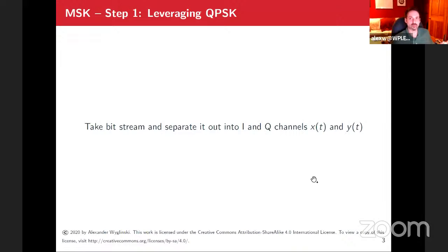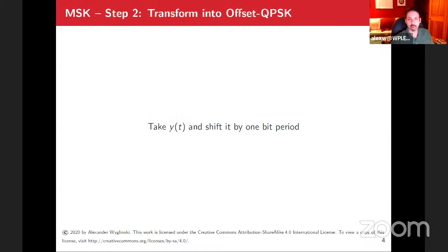They're on I and Q channels, right? You have to be very mindful about the phase transitions. That's still going to be a bit of a pain. But what ends up at the end of the day is you get these really nice waveforms that don't have any abrupt transitions between boundaries, and they combine together. Now, I just did MSK type 2 in your book. Like I pointed out, 5-112 is one cool expression there. And you saw, I was fuddling around and saying, how the heck do you deal with that?